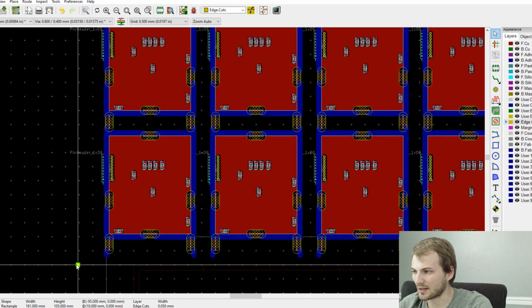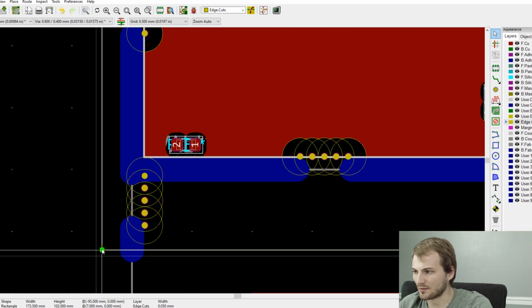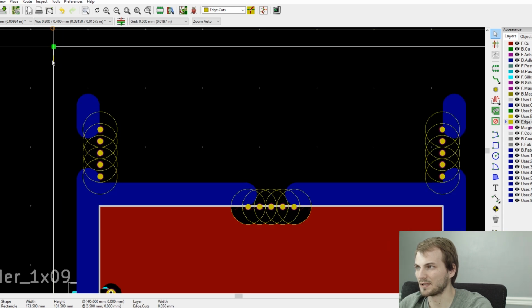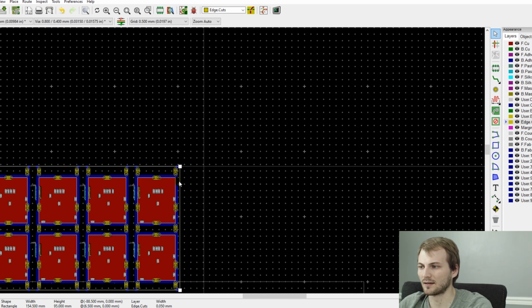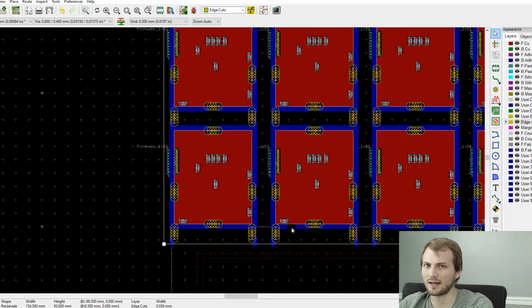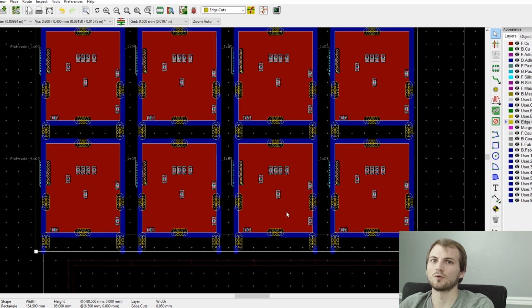So now we can shrink down the edge cuts down to, again, whatever you decide you want your margins on the PCB to be, or on the panel, and that will really depend on who you're using for fab and who you're using for assembly. They'll have design rules which state how much of an edge they want on the front and on the rails down here, which is where the actual board will become depanelized, or where the panel will go on the conveyor rail.